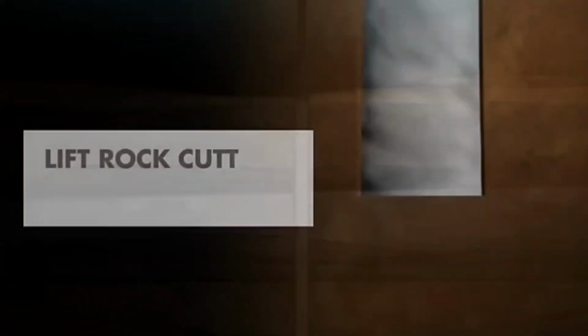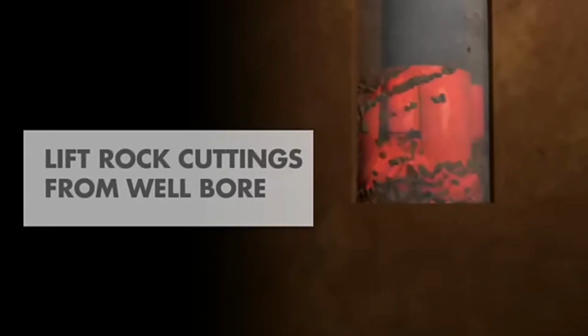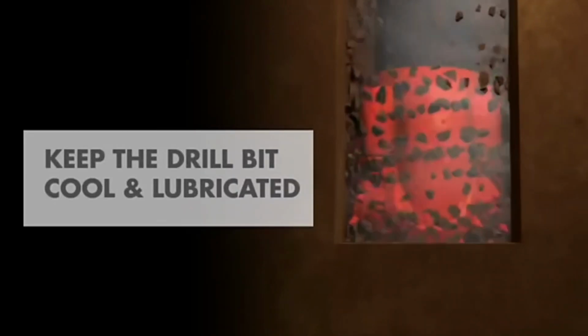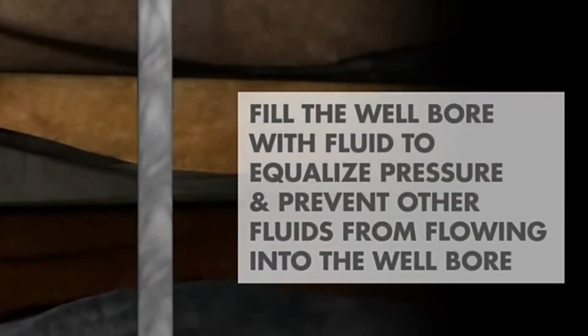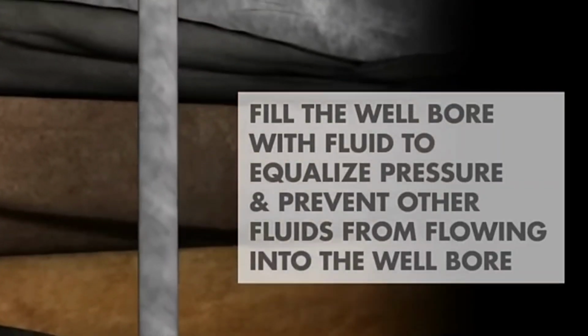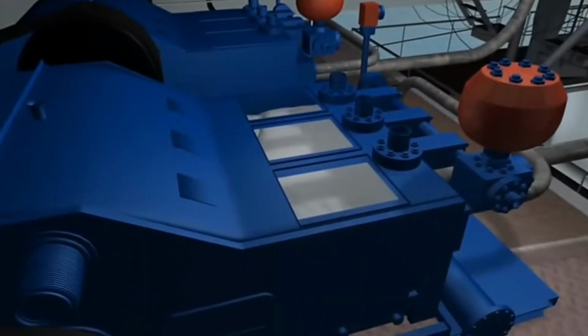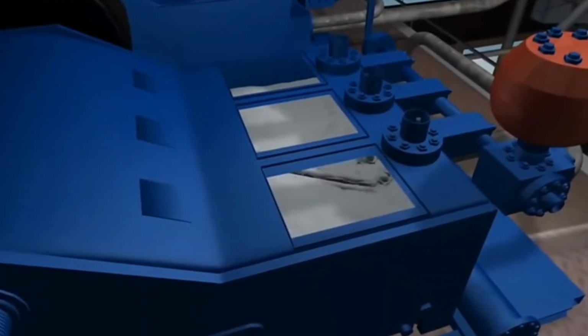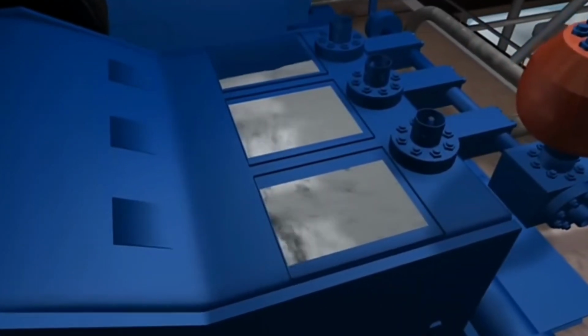Drilling mud is used to: 1. Lift rock cuttings from the hole. 2. Keep the drill bit cool and lubricated. And 3. Fill the well bore with fluid to equalize pressure and prevent water or other fluids in underground formations from flowing into the well bore during drilling. The mud is an environmentally friendly water-based mixture of clay for thickness and fine ground rock or barite for weight.